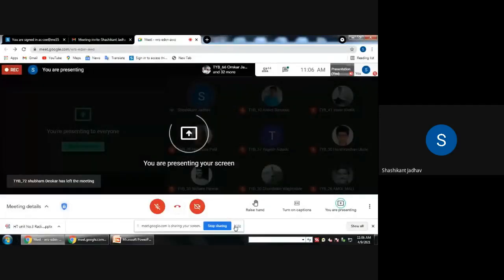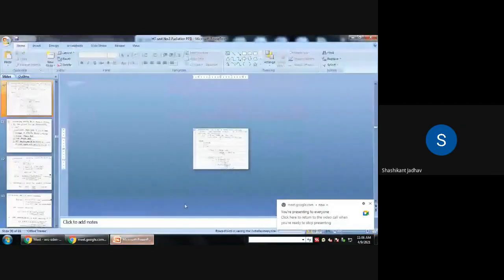So we have considered one hollow enclosure, and that hollow enclosure we have considered as an approximate black body because it absorbs the maximum radiation incident on it. Okay, so this hollow enclosure is used for the calibration of heat flux gauges, thermometers and other radiometric devices. After that we have discussed the laws of radiation. What is the first law of radiation? That is Stefan-Boltzmann law.